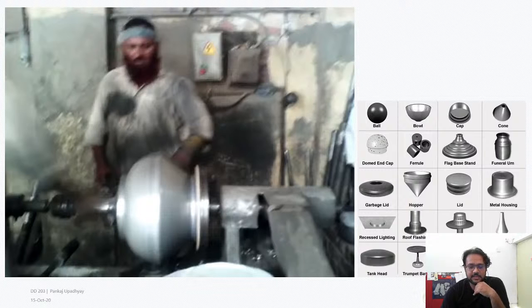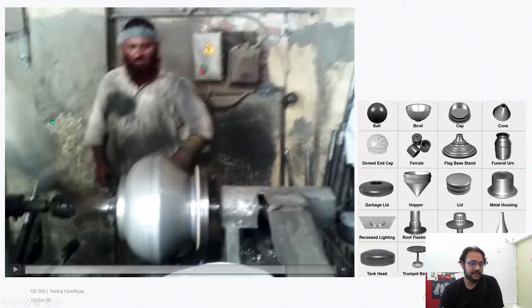So Aditya is asking, if you have a strong machine, by strong I'm assuming you mean something that can apply a large amount of force, can you deep draw using other stronger materials? The main property that is required in the material to be suitable for deep drawing is its ductility. So it depends on the material's ductility. Okay.